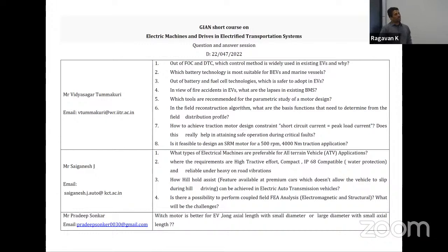Yeah, they are two different though, right? The electromagnetics comes from Maxwell, and then the structural comes from ANSYS Workbench, the original ANSYS, right? So they don't do it together. They will solve one after the other. So I think here he's talking about if you're properly coupling it, where they're actually working together. COMSOL is the one where, as I understand, the equations are actually coupled internally. They're connected internally because they were designed to be part of the same system, as opposed to ANSYS, where they acquired different software and stitched them together. So yes, you are correct.